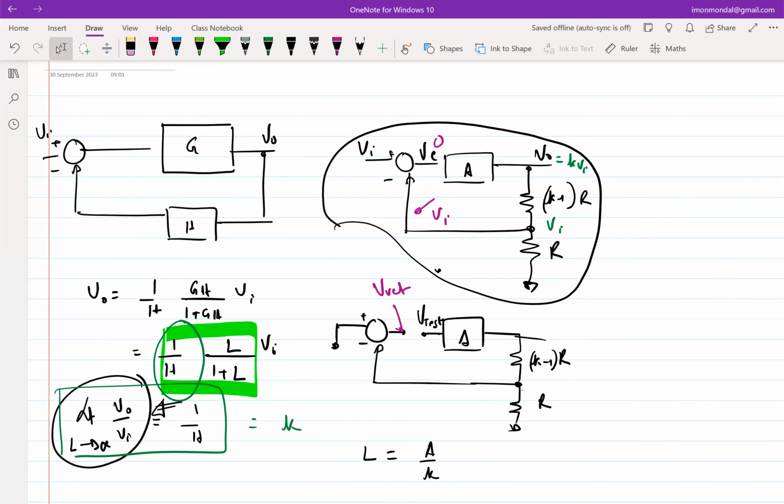Which means that in a properly working negative feedback loop, there should not be any high impedance. Right? Because that's what a loop is supposed to do. A loop is supposed to always hold the output to your desired value. Whatever happens anywhere in the loop, it should not let go of that output. Which means if the loop gain is high, the loop will do anything in its capacity to correct the output. It will pre-distort something, change something somewhere, but it will always ensure that output is whatever it is supposed to be. Right? So you inject anything anywhere, the current should get absorbed without excursion of any voltage.